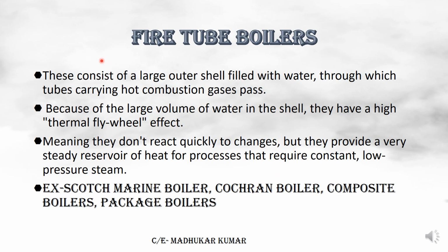Now the fire tube boilers. This consists of a large outer shell filled with water. It's like a tank, through which the tubes carry the hot combustion gases, or the flue gases are passing through, and the generation of steam takes place. Because of the large volume of water in the shell, they have a high thermal flywheel effect. That means if you have a loss of water, you have at least response time.